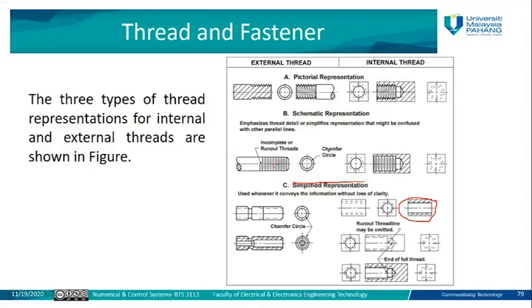They said it's rarely represented in the drawing, but there is. Sometimes they need it, if they want to represent some of the screws for the drilling machines and so on. They need to have some representation to know the dimension, the length of the screw, how many teeth, what is the angle, and so on. So there are some parameters about the thread they need to define when they make this blueprint for the products.